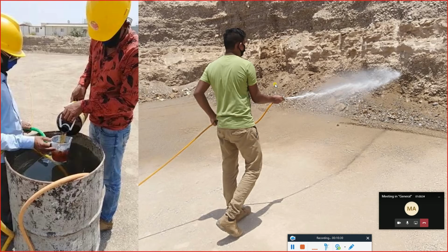Now the main function of the anti-termite is to stop the insects from eating the timber, because later on we are going to use a lot of formworks, and we don't want to have issues related to termites. So after compaction, anti-termite is going to be done, and normally anti-termite is done by a specialized company. The contractor normally is not doing the anti-termite. You need to bring a special company who does the anti-termite, and normally they will give you a warranty of 10 years.